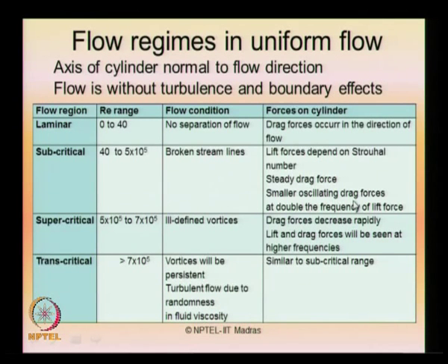The oscillating component of the drag force is very small, more or less the drag force remains steady in the subcritical region, where the Reynolds number is as high as 5×10⁵. Interestingly, these oscillating drag forces occur at a frequency which is practically double that of the lift forces. You can clearly see two distinct frequency components, one on lift, one on drag.